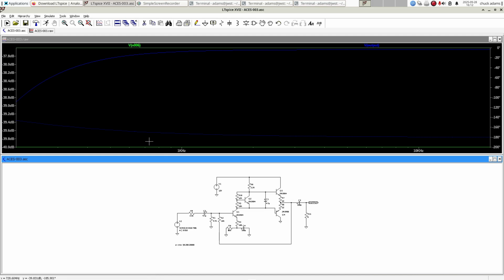And the nice part of this is, from about 700 hertz out to 20 kilohertz, it's flat, almost like an LM386. So that's what we should get from measuring the output with a load on the amplifier and a 10 millivolt signal in.